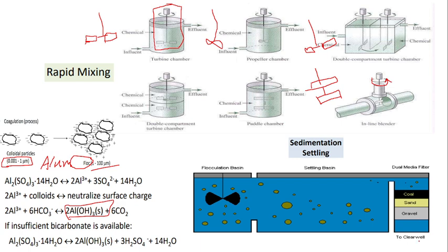In this rapid filtration chamber, you can see they are having a dual media where coal and sand are used, and gravel is a supporting media. When this water is passing through, the small colloidal particles can be separated, and only the fresh water comes out of the filtration process. If no flocculation is happening, all the smaller particles cannot be separated in this filter, because when a larger amount of smaller particles are there, the filter will get clogged. The clogging will happen very frequently, so the filter will get damaged.